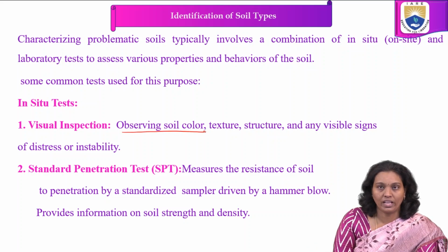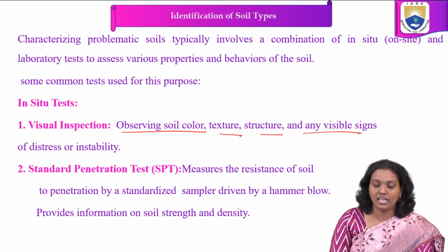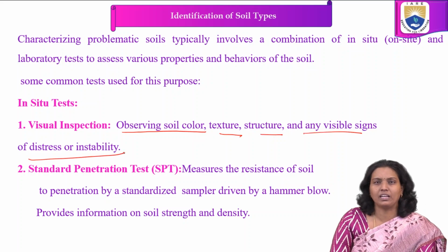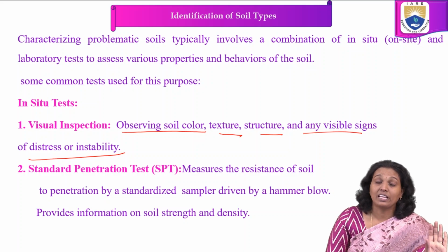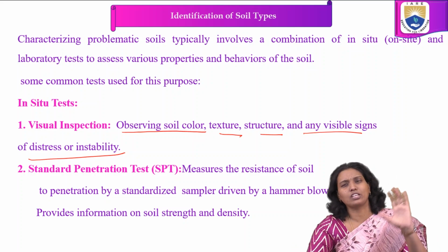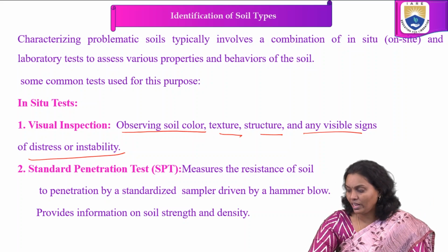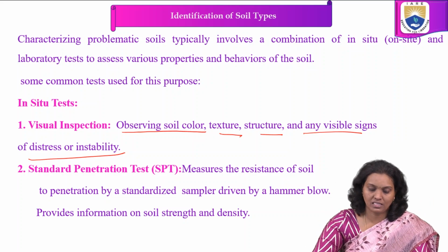We observe the soil color, structure and other visible signs of distress or instability, and we categorize and partially conclude which type of soil it may belong to.